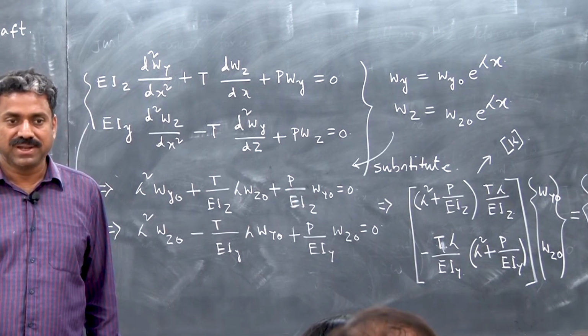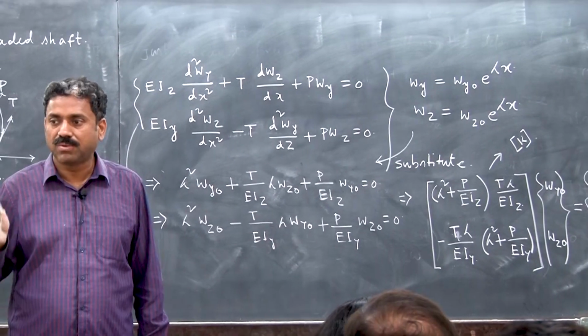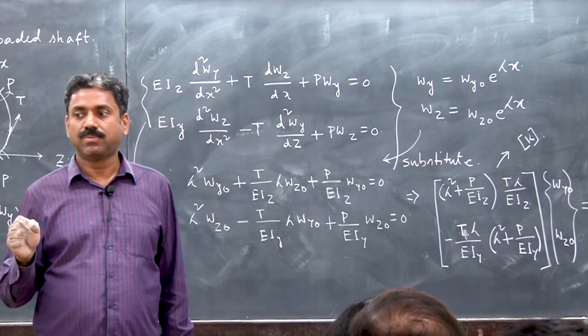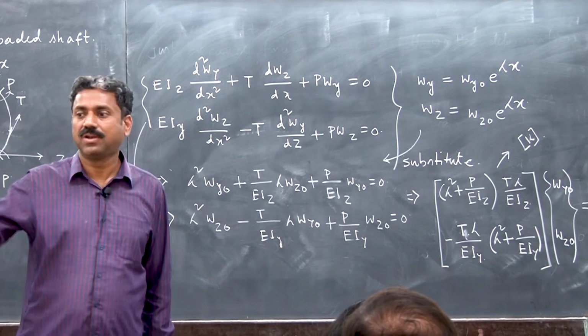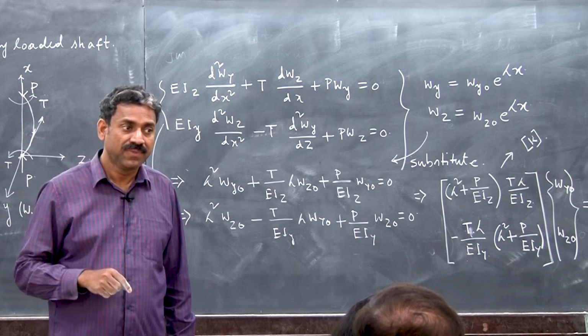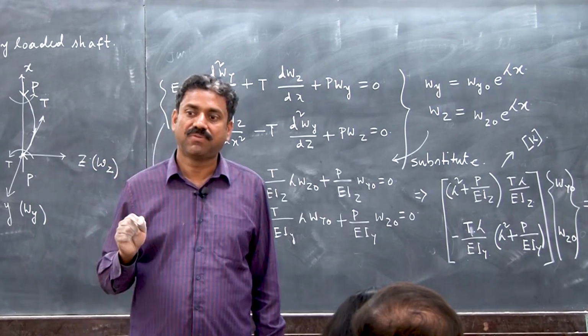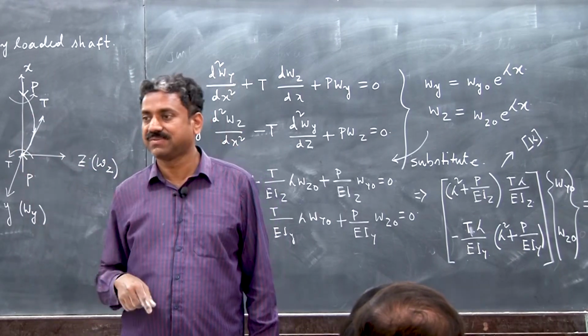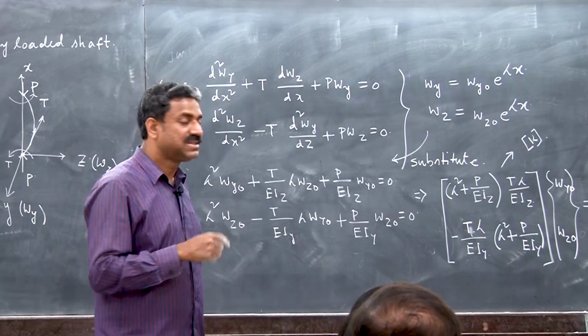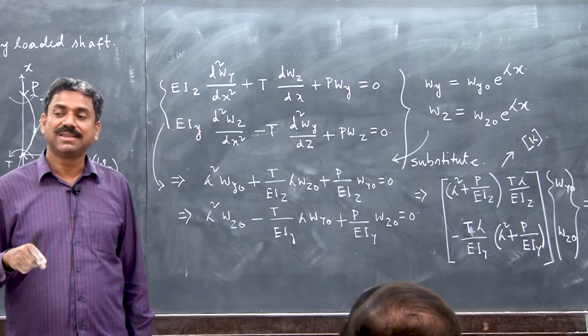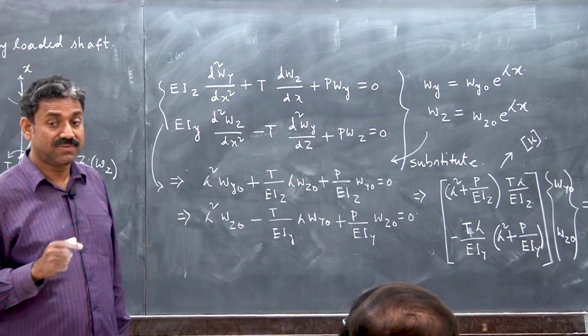If there is a positive energy flow on deformation, if you apply a load at point i, whatever deformation you get at point j, if you apply the load at point j, the deformation should be the same. Why? Because there is a positive energy flow from i to j, and then the same energy from j to i. When it is asymmetric, an asymmetric stiffness matrix occurs in several cases.